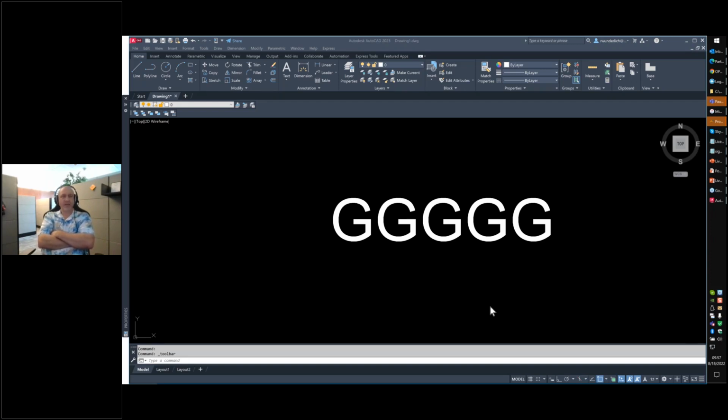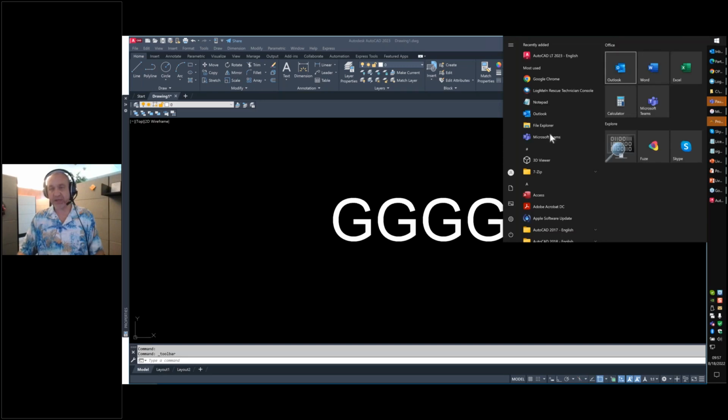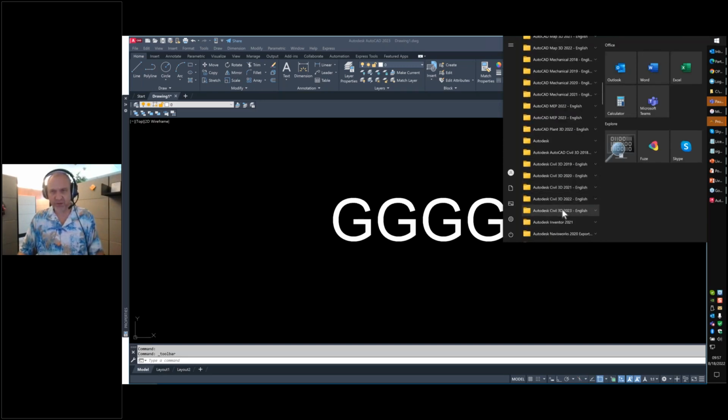It's actually pretty common when things go wrong in Civil 3D, AutoCAD, things like that, that the information you have in here is stored in both the registry and your local user profile. What I typically see, if I go digging deep enough, is that your registry entries, instead of being plain text, get converted to hexadecimal. Once they've been converted to hexadecimal, it reads correctly in Civil 3D, but some of the commands don't know how to interpret that information correctly. And so usually I will come in here, go down to Civil 3D 2022 or 2023, and there's a reset settings to default. I would probably reset the settings, see if the behavior continues, and make sure I've got all my updates.